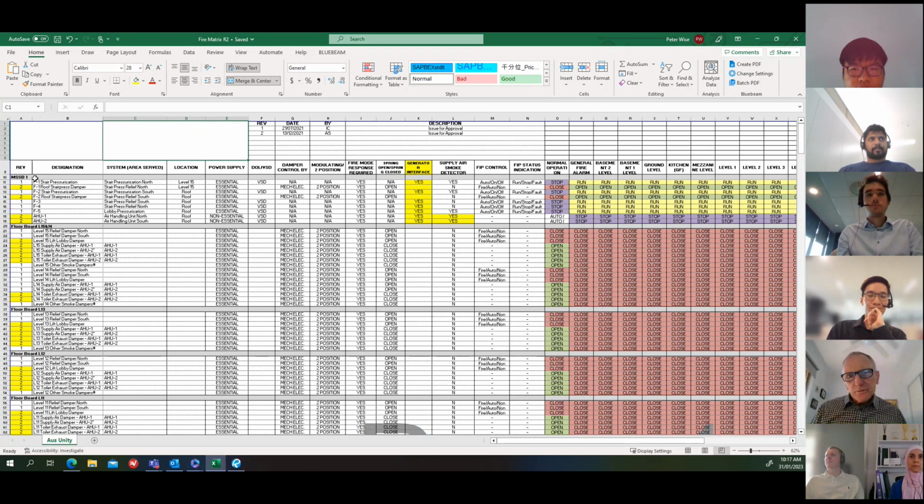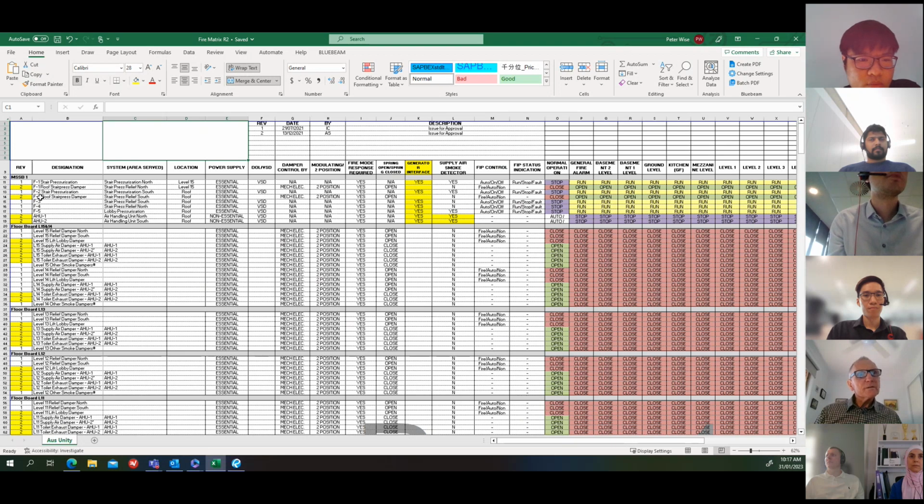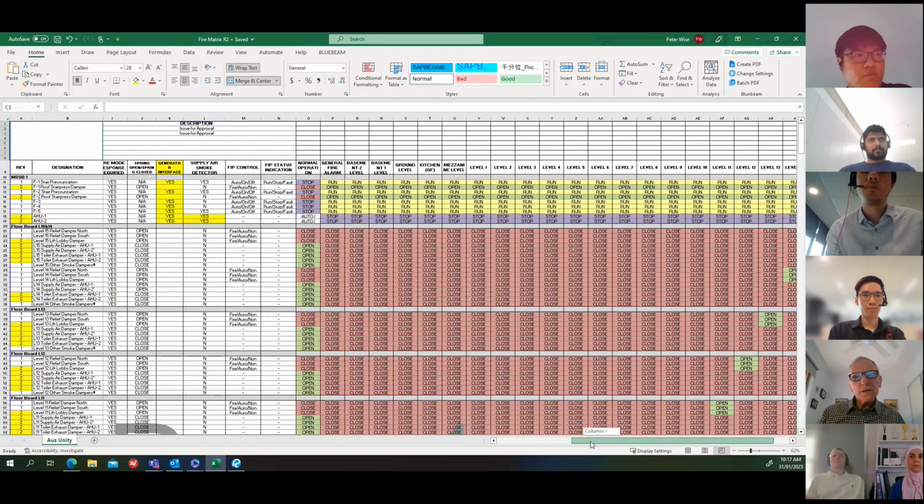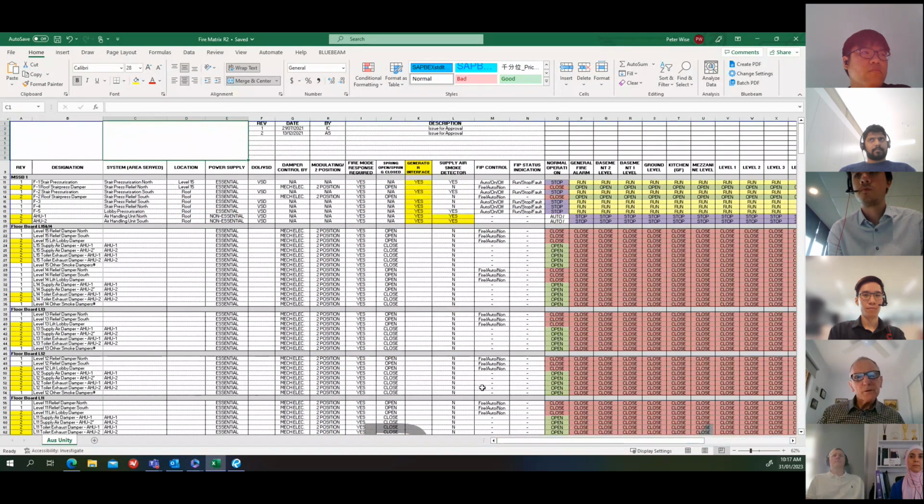This is broken down into switchboards. So there's a main switchboard or mechanical switchboard, MSSB1, and each floor has got a separate board for controlling dampers. On MSSB1, there's some stair pressurization fans. Now this building, if I just scroll across, it's got 15 levels. So it's more than 25 metres high. So it brings in all those requirements in NCC Table E22A that I mentioned before. Okay.